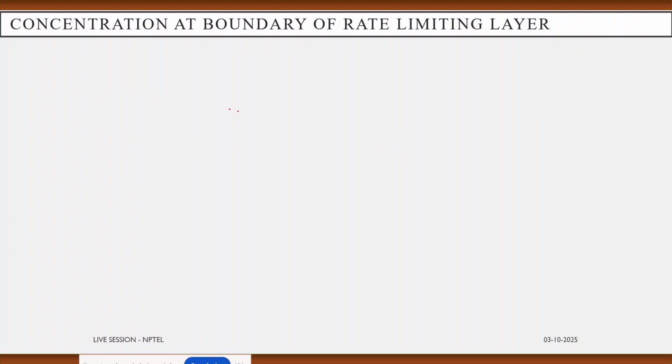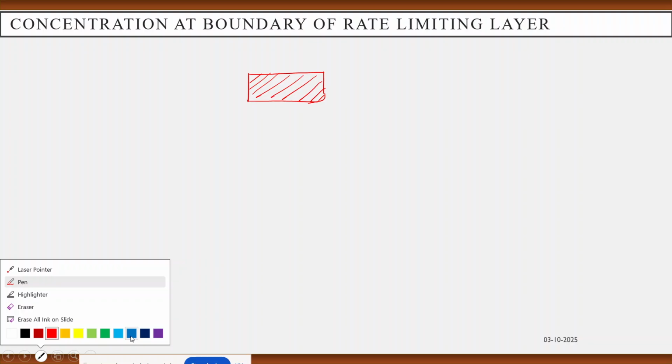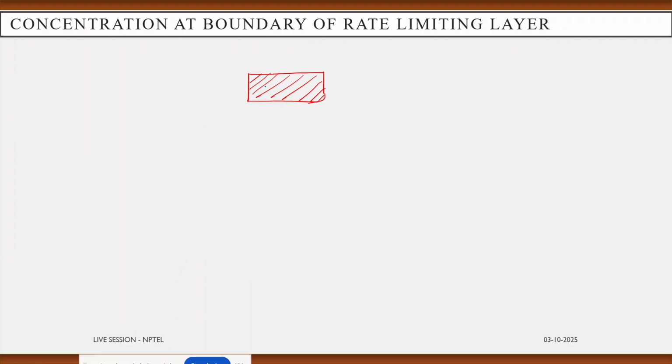So here we first suppose this is one concentration layer in that sedimentation study. It has a certain concentration, which we assume to be concentration C of this layer, and this layer has a rising velocity upward towards the direction of the overflow, that is VL.